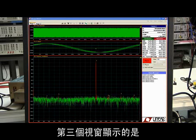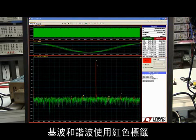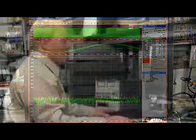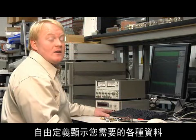The third window shows the FFT of the input data. The fundamental and harmonics are labeled in red, and the yellow line shows the average noise floor. These windows are standard windows. PScope is easily customized to display any data that you want.